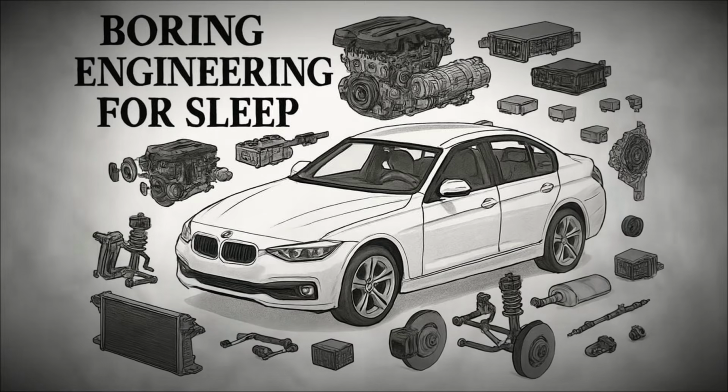Modern cars may also include additional emission controls, such as particulate filters, especially in diesel engines, which capture soot particles and periodically burn them off to keep the filter clear. After emission control devices, the exhaust gases pass through a muffler, which reduces noise by using chambers, baffles, and sound-absorbing materials to cancel out the pressure waves created by combustion.